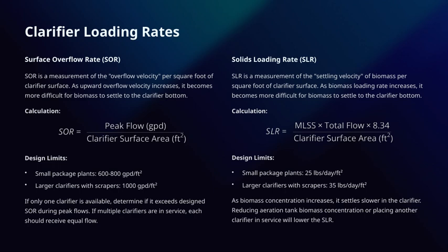Moving on to the solids loading rate, or SLR. This measures the settling velocity of the biomass, again per square foot of the clarifier surface. When the biomass loading increases, it naturally becomes harder for the particles to settle properly.